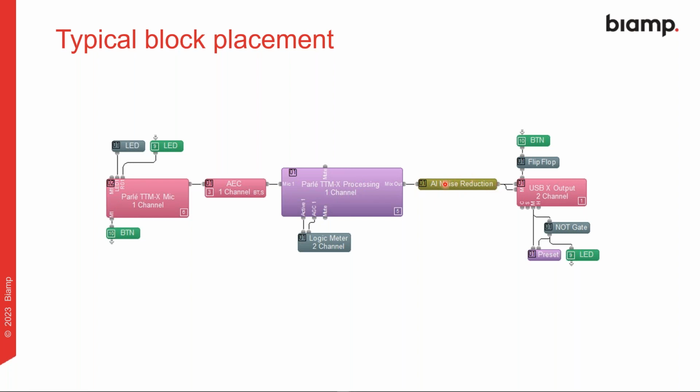And where do you put it? Well, after the mixdown. We haven't added any line rules. That means we haven't made the Tesira software block where you can place it in the layout, apart from the obvious ones. So you can't put it in front of AEC, which is true for any block of this type. It needs to go post AEC. If you've got multiple microphones, you've only got one channel, so it needs to go from the mix.